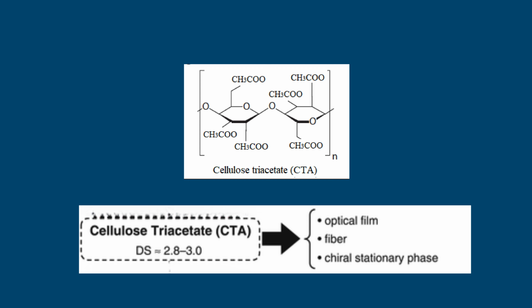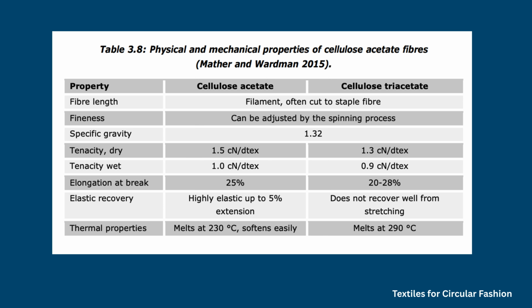Cellulose triacetate, CTA. CTA approaches complete acetylation with degree of substitution values near 3.0. Compared with cellulose diacetate, CTA demonstrates higher crystallinity, superior heat resistance, greater dimensional stability, and excellent chemical resistance. Because of its exceptional salt rejection and chlorine tolerance, CTA became the benchmark material for early reverse osmosis membranes and remains widely used in forward osmosis and desalination systems.